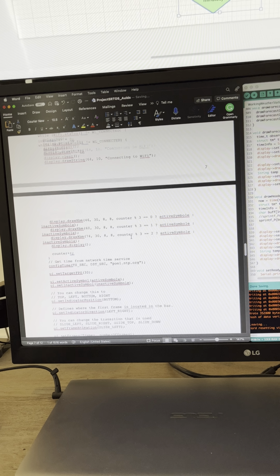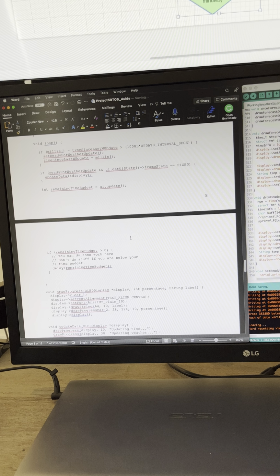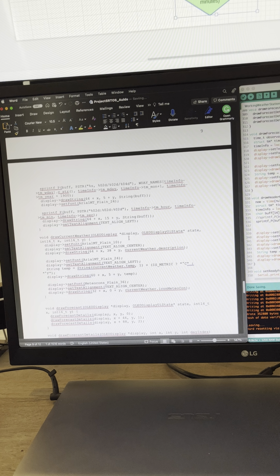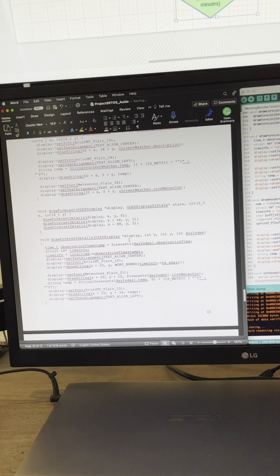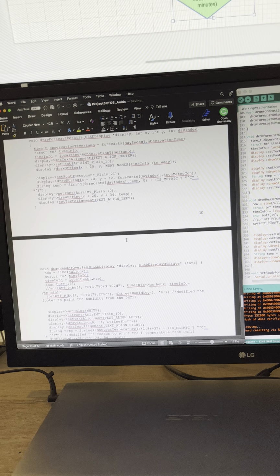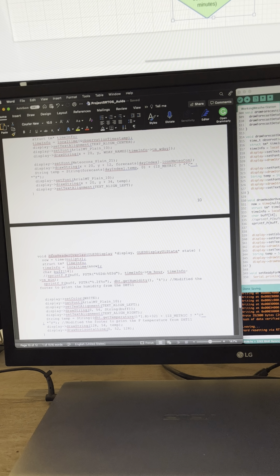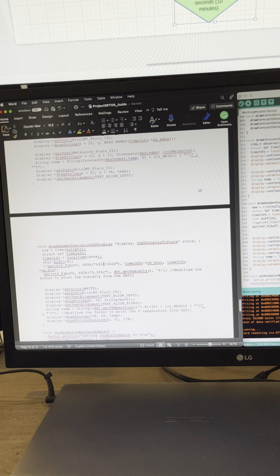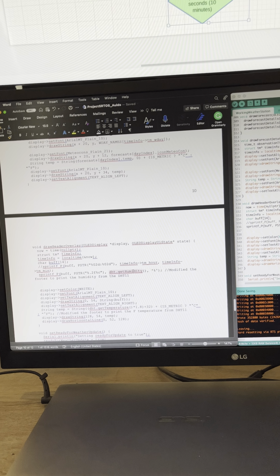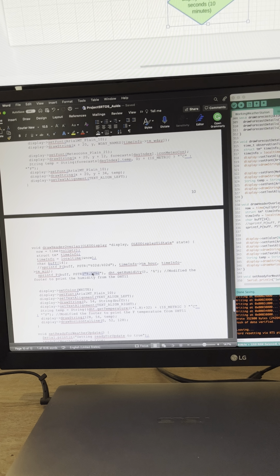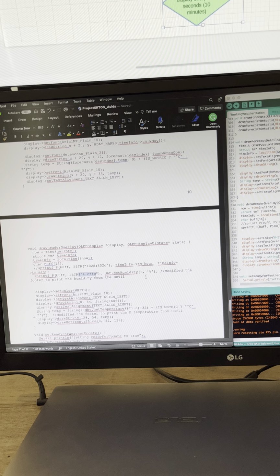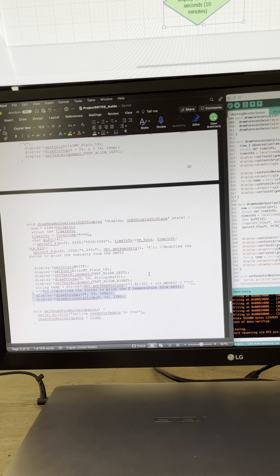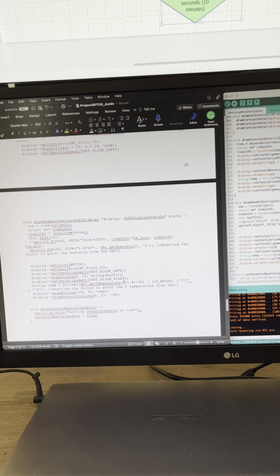And here for the draw header overlay, which is what I'm calling the footer, I commented out where he printed out the time, and I changed it to DHT get humidity with a formatter, so it would print 2 decimal places and then a percent symbol. And then I also modified the temperature that displayed at the bottom to display the DHT temperature, and here I convert it to Fahrenheit.